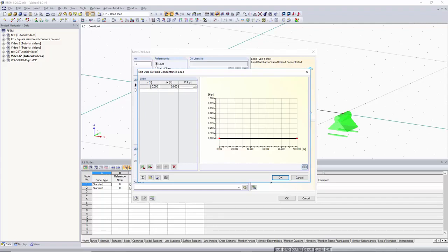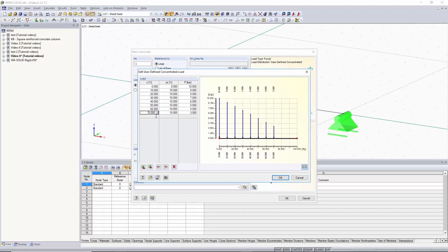So if we wanted to start our point loads at the very first node, and we want the first point load to be 10 kips, and then the next one we would like to start at 10% away from the start, and we want this to go down in a linear fashion, so we'll have 9 kips. And then if you follow this, the program's smart enough to recognize that this is a pattern you would like to make, so then you can easily just click on the next cells and the program will automatically create and fill in the next cells for you, which is pretty nice.